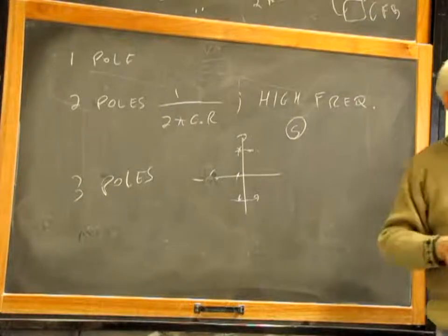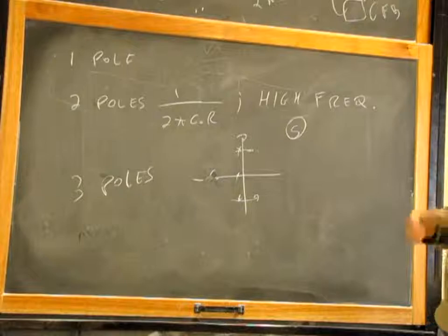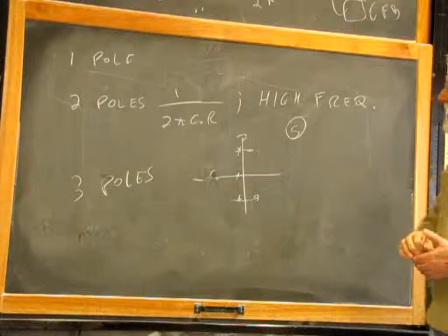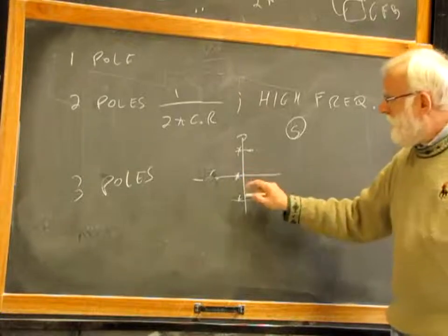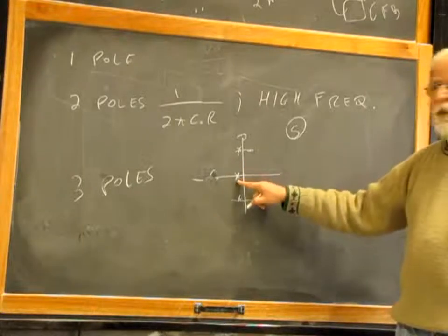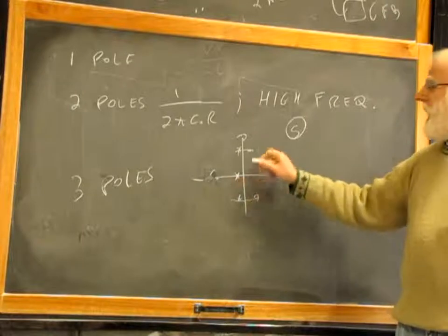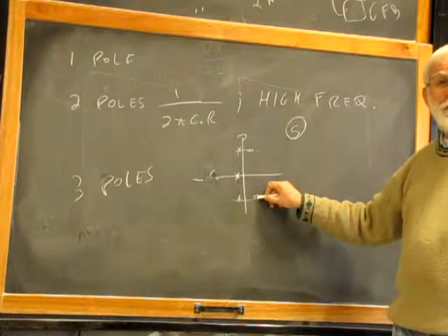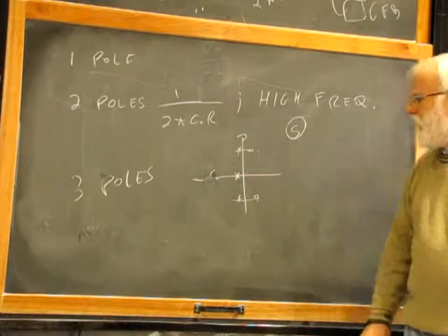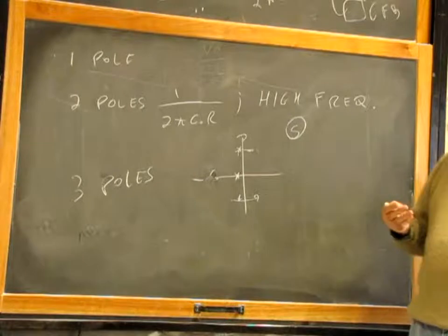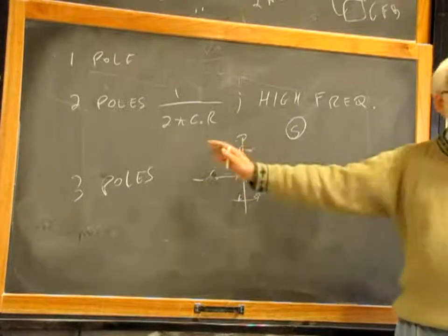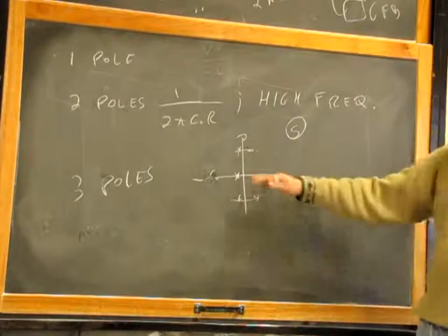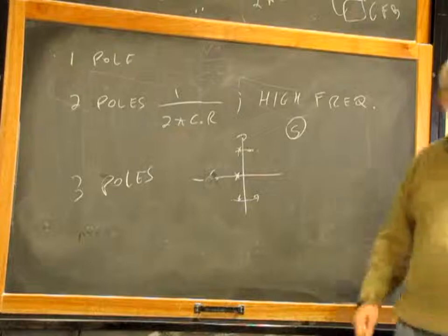So in some cases you can justify this. It's just a hand-waving proof, not a rigorous proof, that you have 3 poles and this model is correct. So this model tells you that you have one low frequency pole, that is what you have to worry about, and these 2 poles that can move to the right-hand plane if your duty cycle increases above 0.5. If you add a compensation ramp, these 2 poles are moved to the left and you don't have to worry about it. Okay? That was the situation in the 90s or a little bit later.